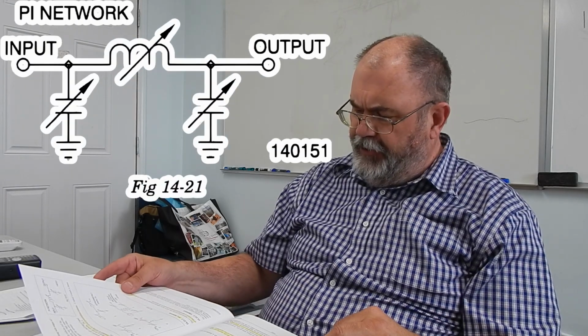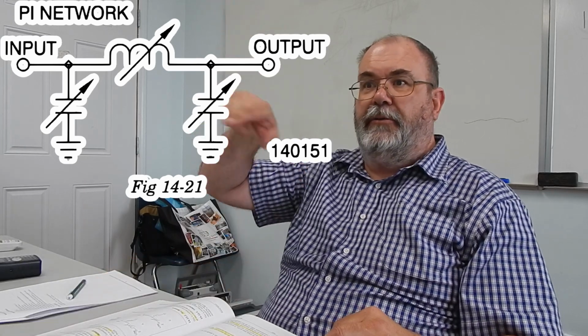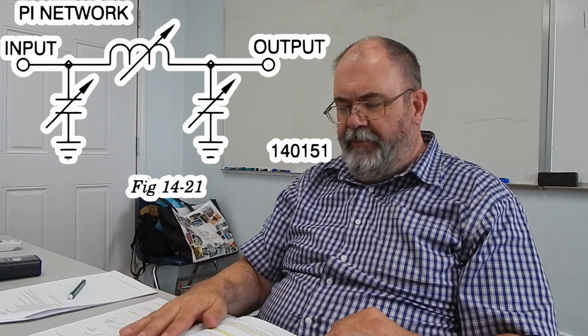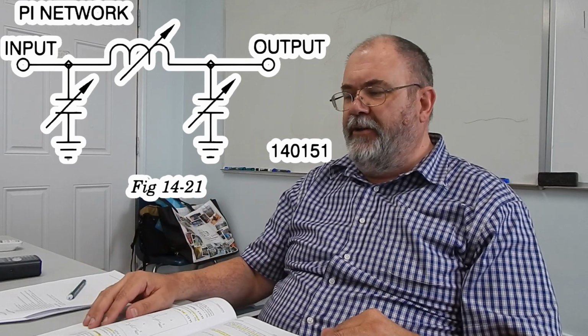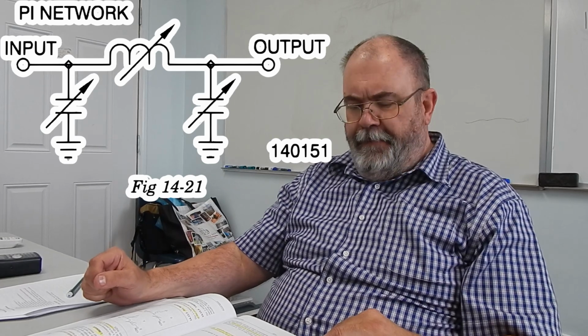So the next thing to do is talk about the Pi network, and we're going to be at the bottom of page 14-22, and the Pi network is shown in a nice little diagram on the top of page 14-23. The reason they call it a Pi network is you've got the 2 variable capacitors and a coil, and they look like the symbol for pi. Capacitor, coil across the top, capacitor going down. They look like a pi, so that's where it came from. The Pi network gives the widest range of impedance transformation of any design. So if you want to be able to tune a wet noodle on 160 meters, you need a Pi network. Okay.